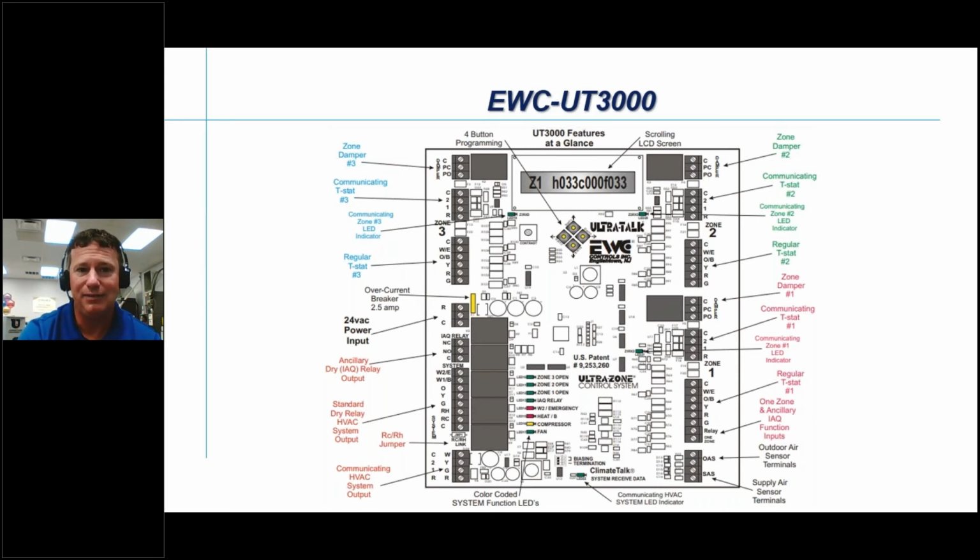And if you install a Daikin Fit, you don't have the option of operating that. That's 100% inverter with an electronic expansion valve coil that is fully communicating with whatever system that it is tied to, and it has to be Daikin communicating now. It can be on the CTKL4, or it could be on the Daikin 1 Plus, because they're still talking in that same DC communicating voltage, right? That same platform that's going to stay around, because they are going to continue. That is their focus now, is to stay with this.